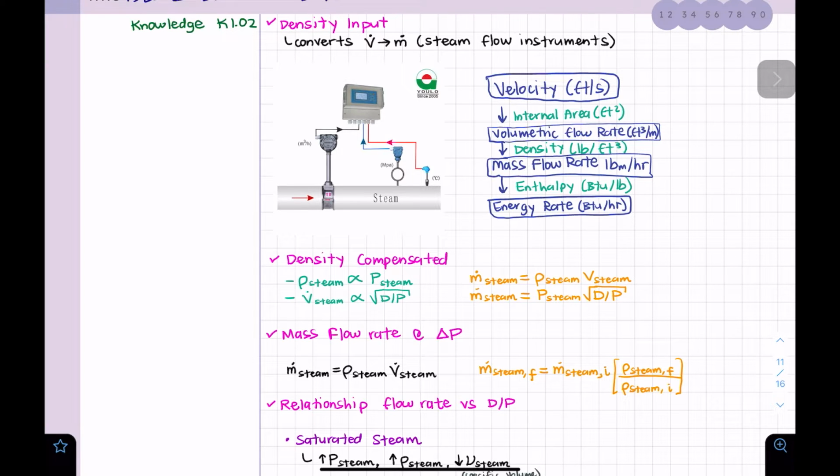And to accurately measure this, we need to have this functioning very well. And the temperatures that are associated with steam flow measurement are often quite high because we're trying to measure steam. And these temperatures can also affect the accuracy of the measuring electronics. So that's why sometimes we have like some tolerances. Also, this can be affected by moisture and impurities from the steam.